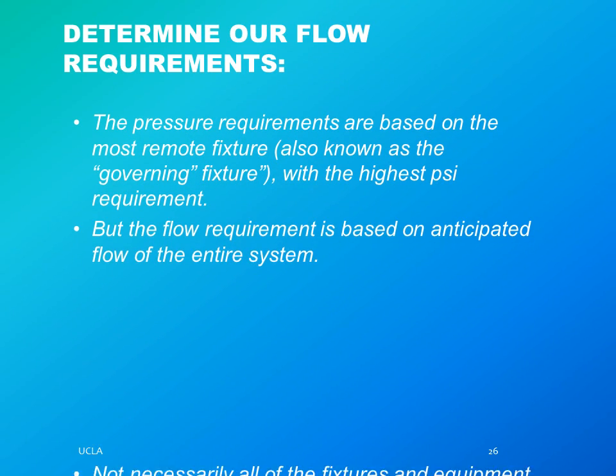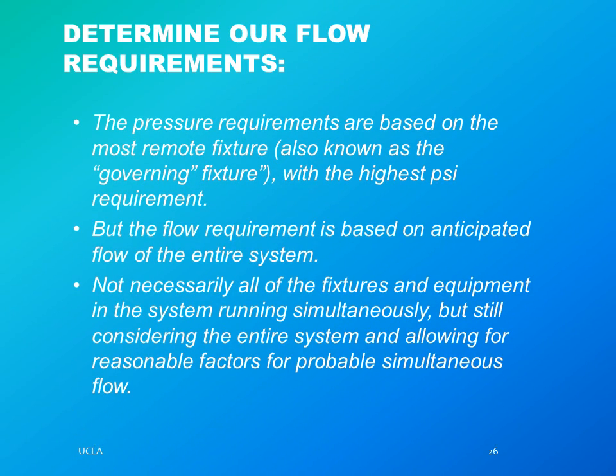What about flow? So to determine our flow requirements, remember the pressure requirements are based on the most remote fixture, and that is the fixture with the highest PSI requirement, usually at the highest part of the building and the furthest away from the pump.